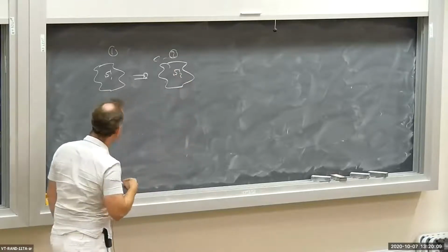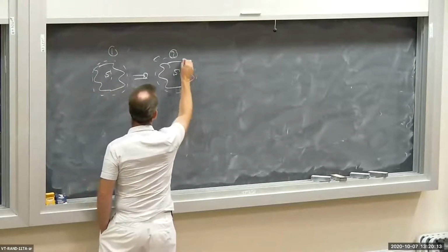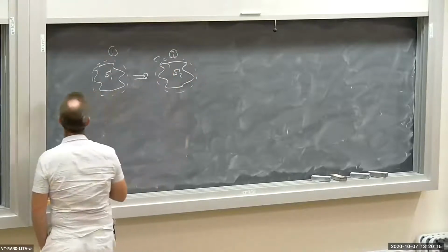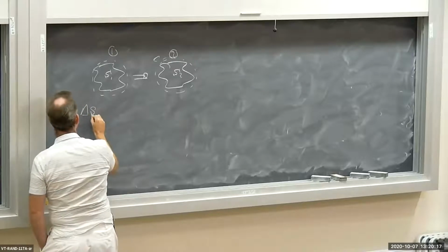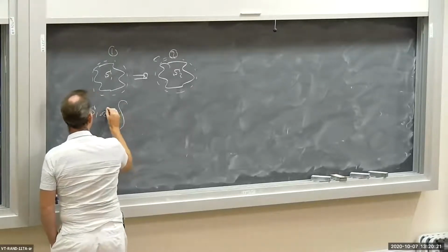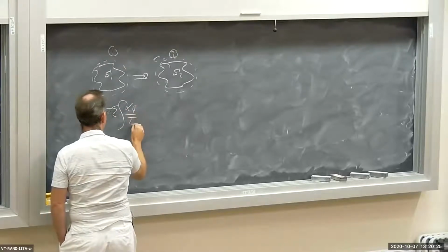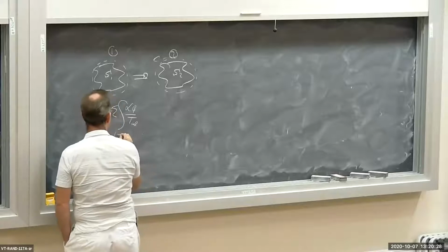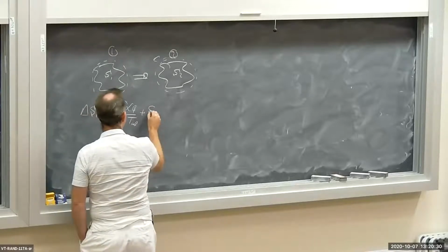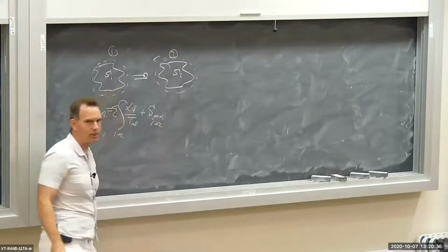If we write the entropy balance on our system, we see delta S from 1 to 2 is equal to the integral of del Q over the interaction temperature plus entropy generated due to irreversibility over the process, okay?